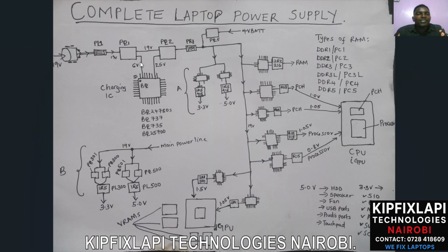The gate is a pin which sends or receives the signal from the control IC. Every MOSFET within the laptop motherboard has a control IC. This MOSFET does not switch power by itself. It needs the assistance of a control IC. So each and every MOSFET within the motherboard has a certain control IC. For example, the control IC for MOSFET 1 and MOSFET 2